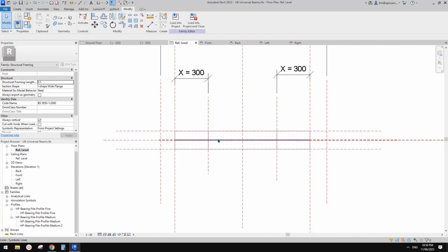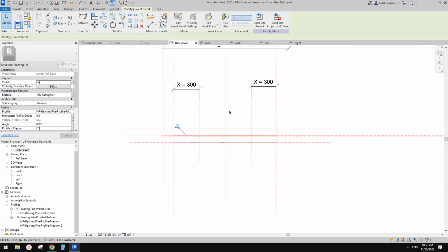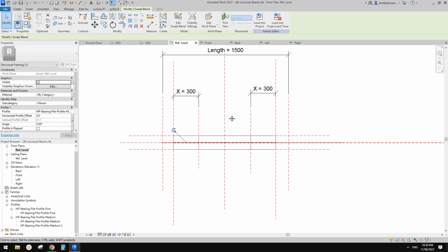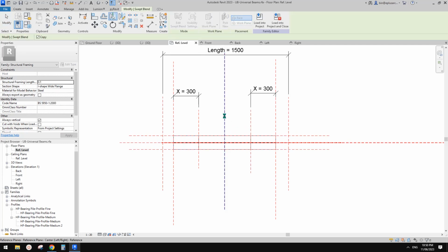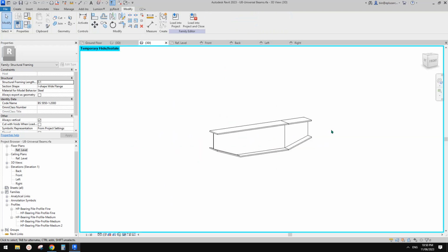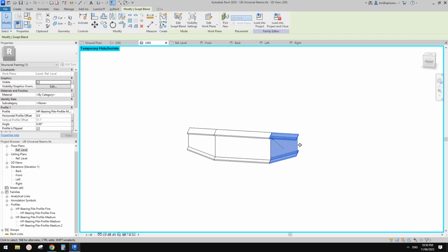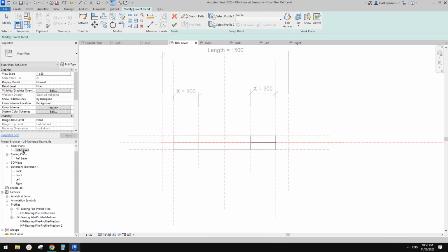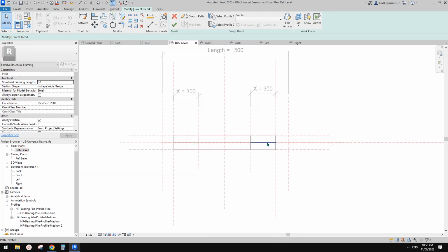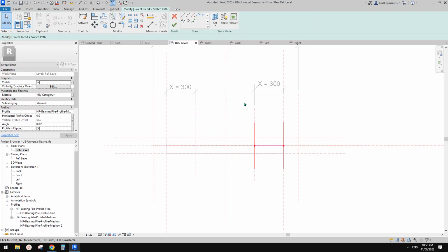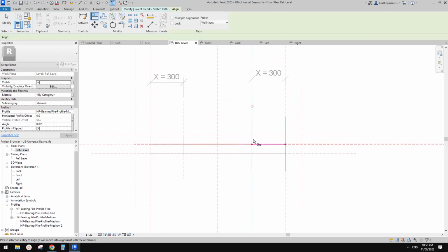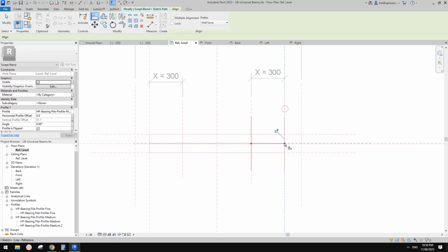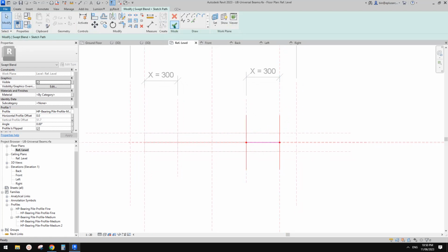floor plan. I'm going to try and see if it works or not. So usually if we mirror, okay, so we'll go here, right? So looks great, but it might not constrain properly. So what we need to do is just go edit this again, and then let's go to floor plan because we need to align the path onto the reference plane. Okay, so you can use AL and lock. AL and lock. Okay, so I think all good.